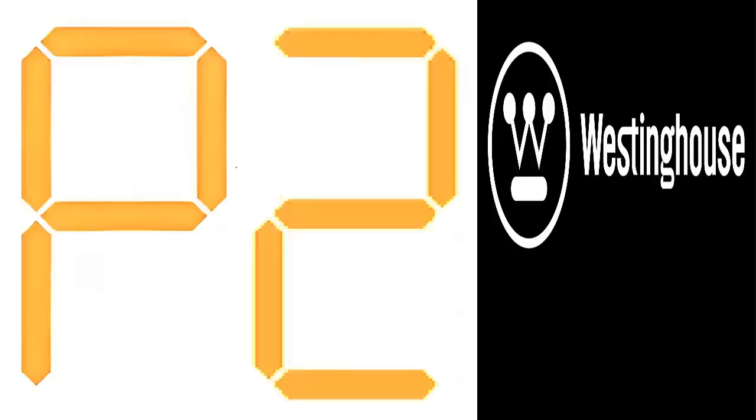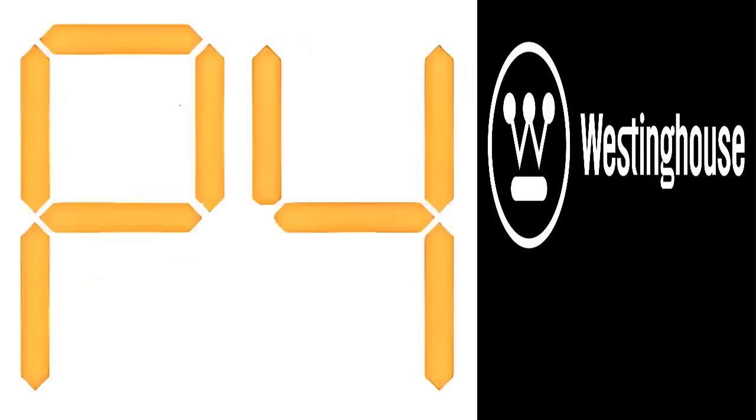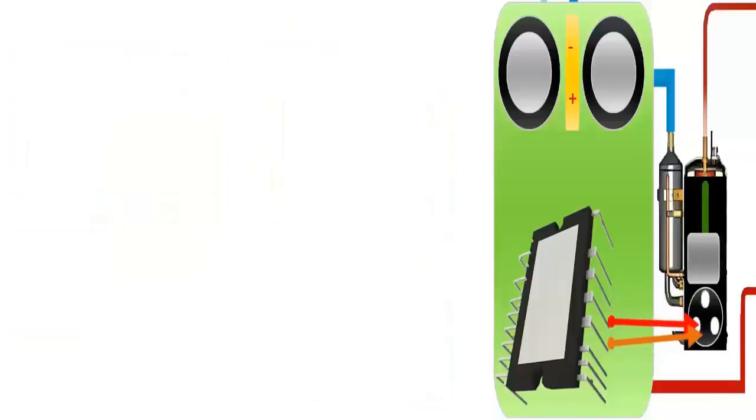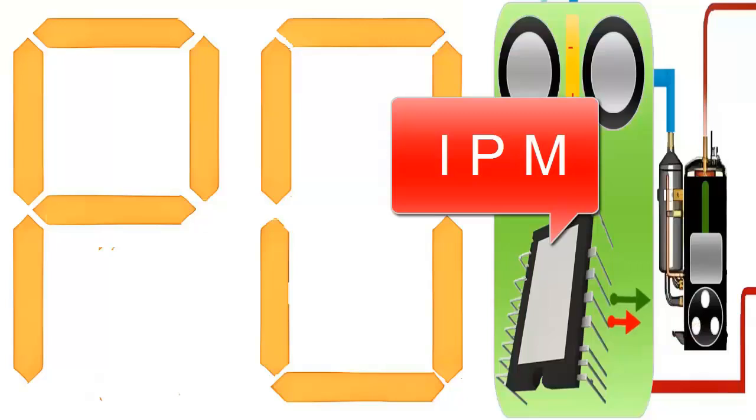Now, we will examine the protection codes P0, P1, P2, and P4, followed by a general troubleshooting procedure. The protection code P0 indicates a malfunction of the Intelligent Power Module, IPM, or protection against excessive current in the insulated gate bipolar transistor, IGBT.